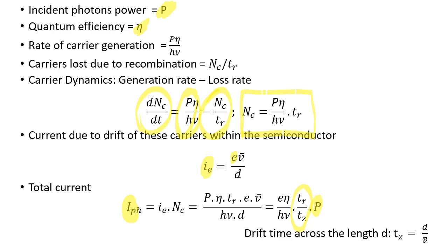What that means is, remember that my detector block is charge neutral. So imagine the electron quickly goes across the detector, goes into the external circuit. Now you see that because the electron has gone out of the semiconductor material, it needs to draw another electron from the connecting wire on the other side.